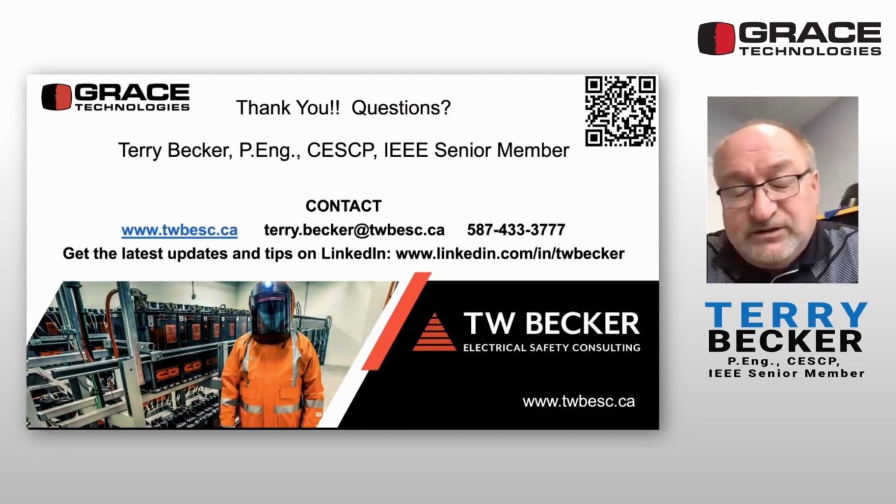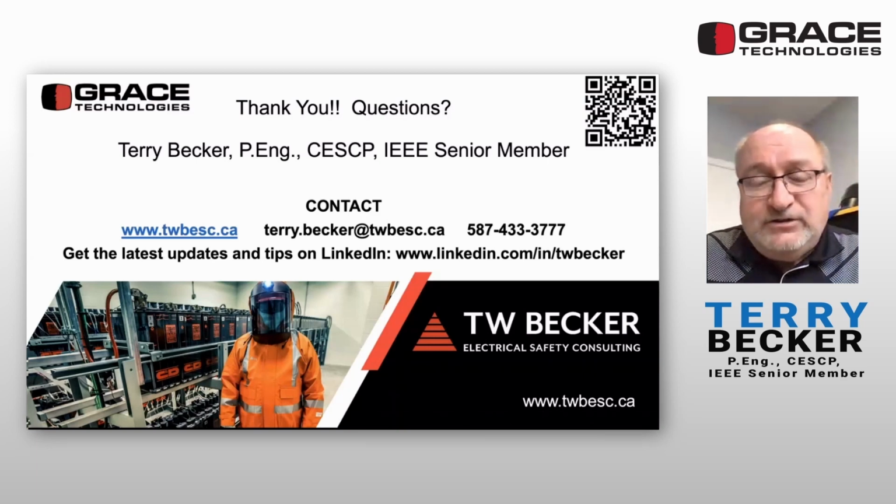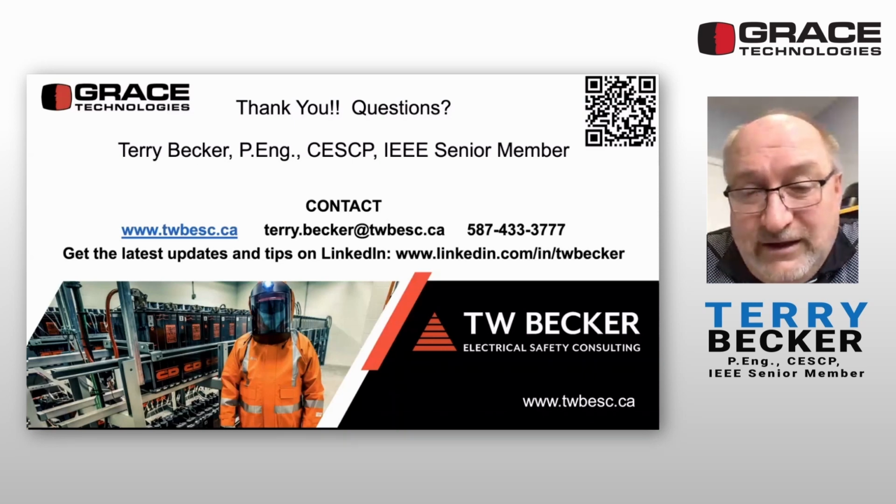And this question is systemic with what I see about the energized electrical work permit in 70E and Z462. It's been misinterpreted. It says that you need the permit whenever a worker is exposed to arc flash and shock, unless it's exempted. It provided 4 exemptions. And then all along, I said, we need to clarify that you don't need the permit to operate, open or close circuit breakers or disconnect switches. You never did, right? That's an operating function.